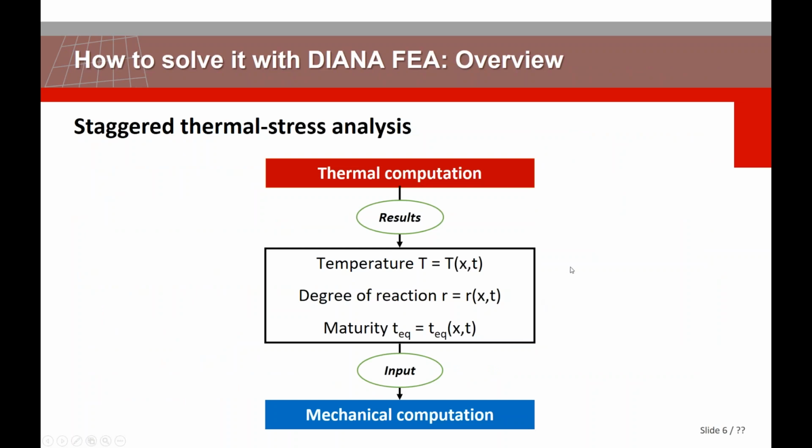Now we can talk about how we solve it in DIANA. This is an overview. Our concept is staggered thermal stress analysis, or semi-coupled thermal stress analysis. Firstly, we compute the thermal part, and the results, for example temperature, degree of reaction, and maturity of concrete, will be used as input in your structural computation.